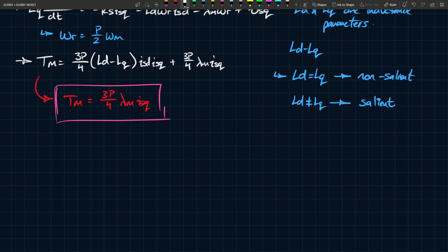But let's also look at the power losses for a second, the electrical power losses. So let's say P loss E is equal to 3 times RS, which is the winding resistance, times the current, which is IS hat over root 2, squared. The reason I'm using 3 here is because these are usually 3-phase machines, and that means there are 3 such windings, meaning the loss is triple what it would be for a single RS. And this results in 3 over 2 RS.